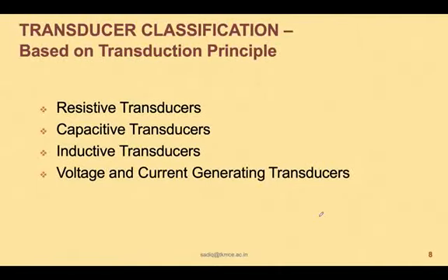Transducers can also be classified based on the transduction principle. That is, if a physical parameter that is sensed by the transducer is converted to a change in resistance, it is called a resistive transducer. If it reflects in a change in capacitance, it's a capacitive transducer, like that. There can also be voltage and current output generated by the transducer, as we have seen in the case of a piezoelectric device or in the case of LVDT. So, based on the transduction principle also we can classify transducers.